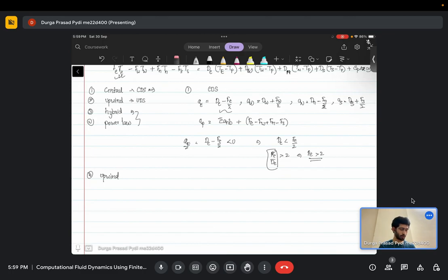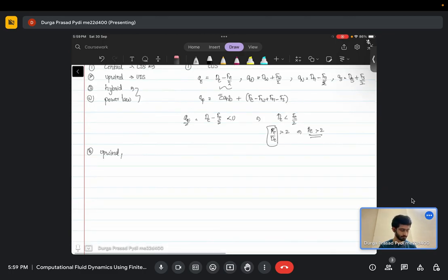So in the upwind scheme, the idea is this. You have P, the east face and the east cell. I need to approximate the value of phi at this east face. In central difference, we are taking information from both east and west. This goes back to when we were discussing the types of equations. An elliptic equation needs to take information from all directions, and a hyperbolic equation has some directionality associated with the information flow.